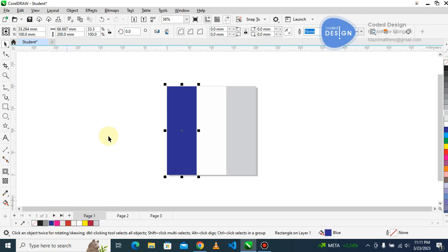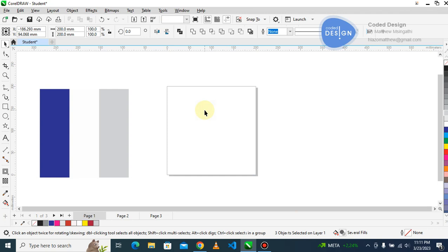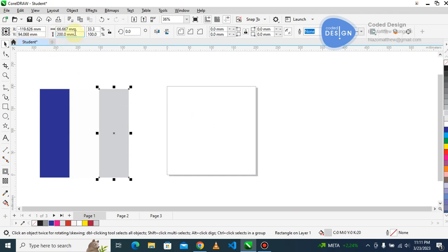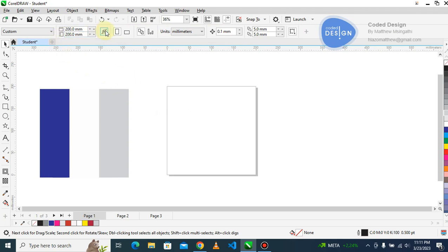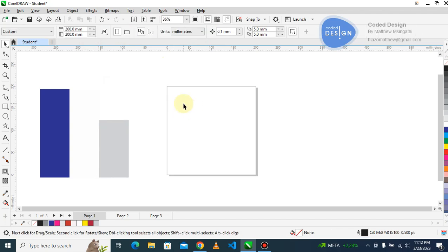What you must notice with Corel Draw is that whenever you click something, this will change according to what you have clicked on. At the moment I have clicked on the page. That's why here on the property bar we can set properties of the page. Once we click a shape, this automatically changes and gives you more possibilities for the selected object. When we want to go back to the previous property bar, we can just click anywhere on the page.